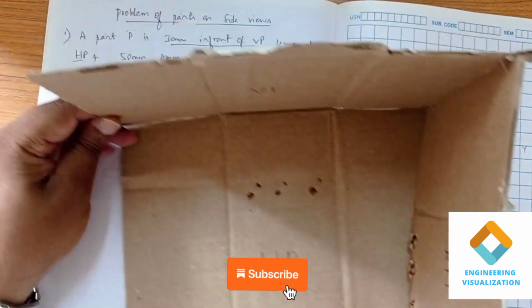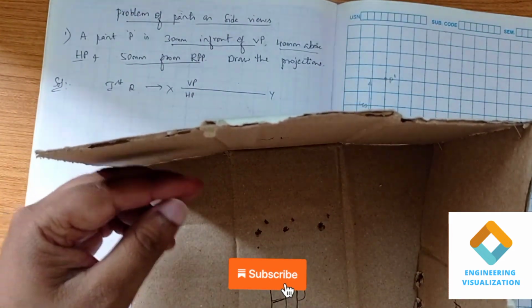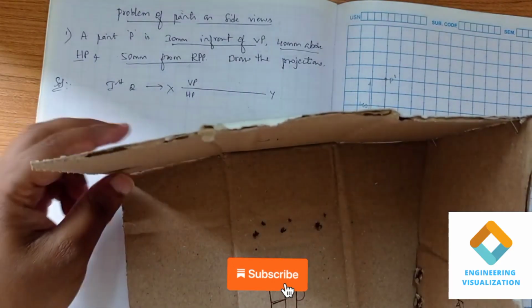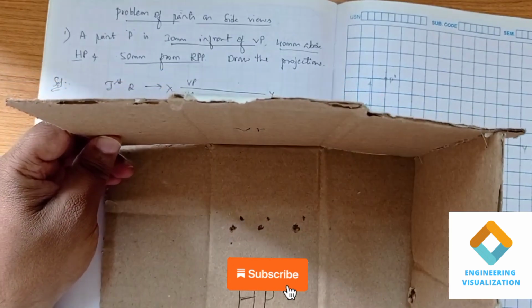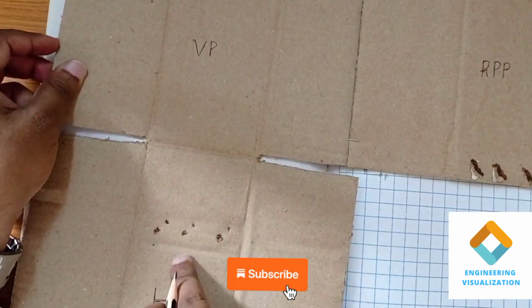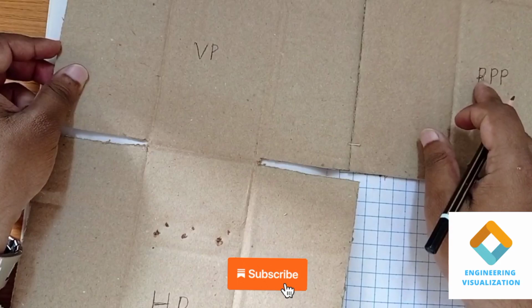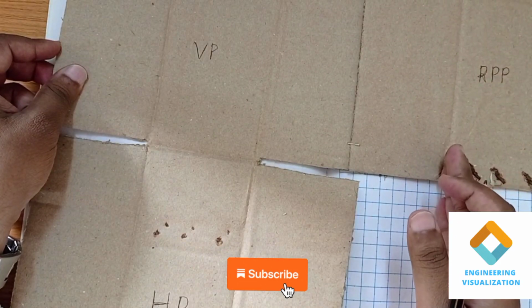Okay. So in this problem he is mentioning that a point P is 30 mm in front of VP and 40 mm above HP and 50 mm from the RPP. So it will be adjacent to the vertical plane. Okay, when it is drawn in orthographic, it will be like this. Front view, top view, and this front view is connected with the side view. So for this RPP we will be drawing another x1 y1 line at a distance of 50